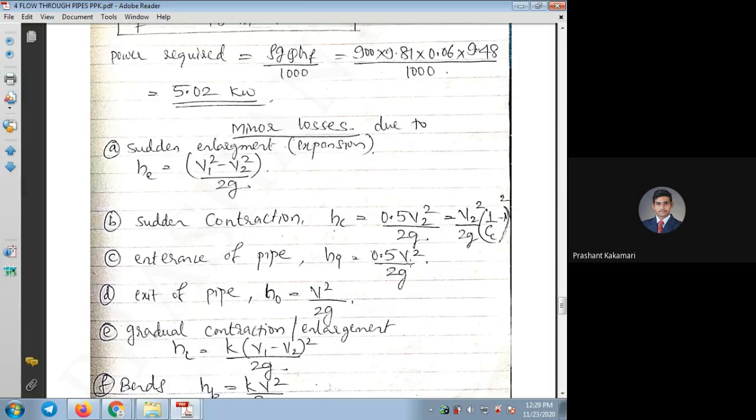it is negligible, a very small velocity from the sump or the big tank, and whatever velocity is there is flowing only in the pipe, because the tank we cannot consider as a pipe with V1, so they are not numbered. So without a number, it means the velocity which is flowing in the pipe itself. So that pipe is connected to a tank of any size, shape or dimension. In such a condition, we are just calling it V square by 2G. So whenever this V square comes, just remember it is the pipe velocity.